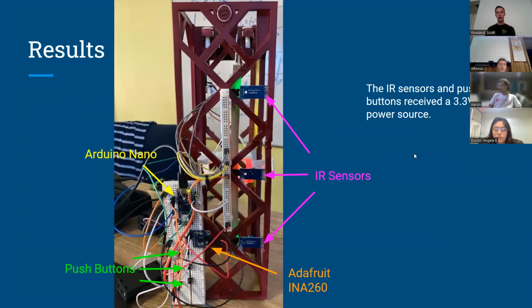As you can see here on the different circuit boards, we have the Arduino connected to all of our inputs and our outputs. Over to the right of the Arduino board, it's just a positive and negative terminal that was taken from a separate breadboard, and that's how we connected all our IR sensors, both to the frame of the 3D printed shaft, as well as back to the breadboard without making things too messy.